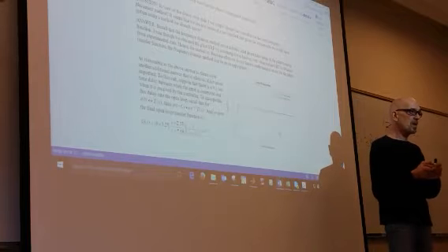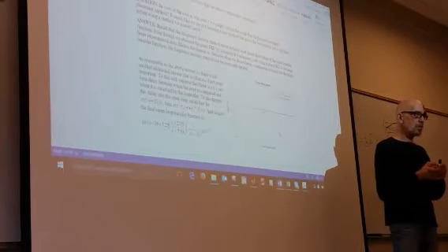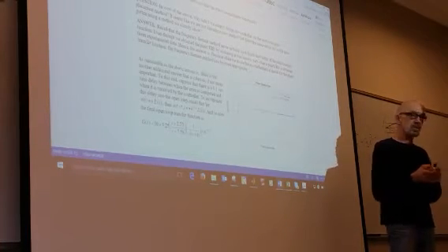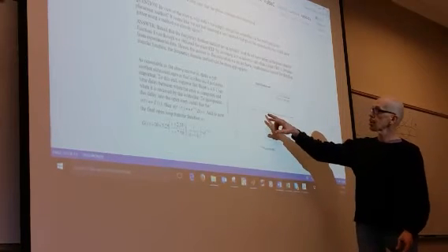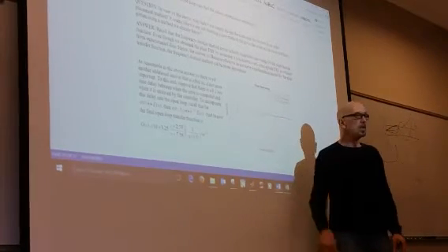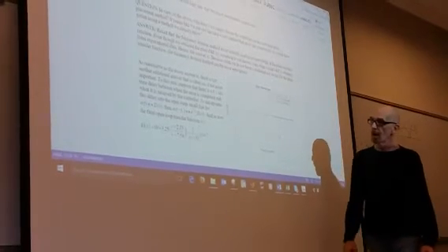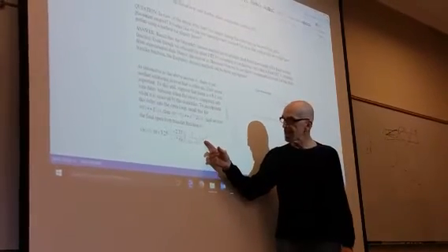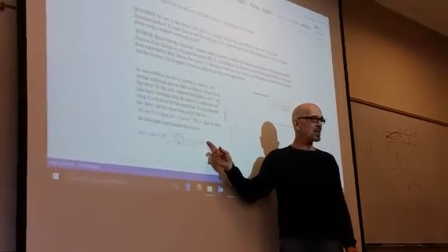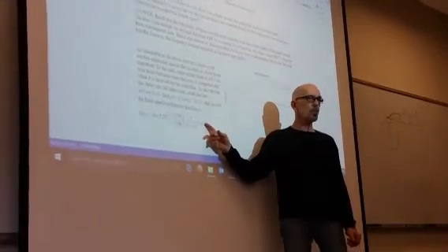This is a 0.1 second time delay between when the error is computed and when the controller receives it, and this is the resulting closed loop response. It's in red. What happened? Well, the plant now has e to the minus 0.1 s in it, because that's the Laplace transform of a time delay.